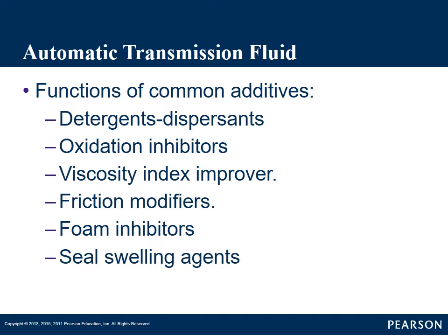When we go to apply clutches, we've got to apply fluid to the back of a piston, and the seal is on that piston so fluid doesn't go by the piston and vent out, and we don't apply a clutch pack. And again, this will make more sense when we get into the internals of our transmission and start talking about clutch packs.